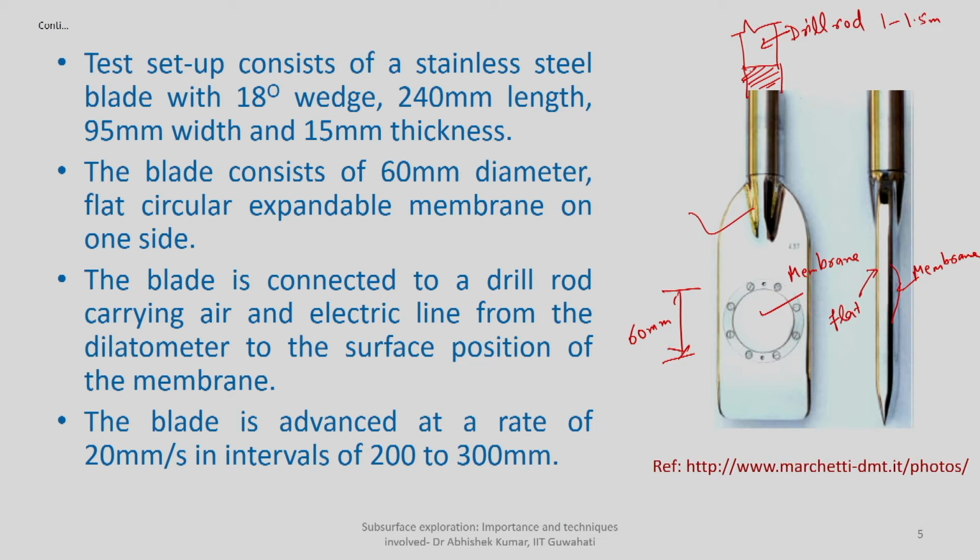You have to understand the depth of exploration, because all these drill rods are hollow. There are some measurements, and some pressure you have to apply from the surface. So every time you put in a drill rod, you have to pass 1 or 2 cables, particularly for pressure application as well as field recording and field measurement.